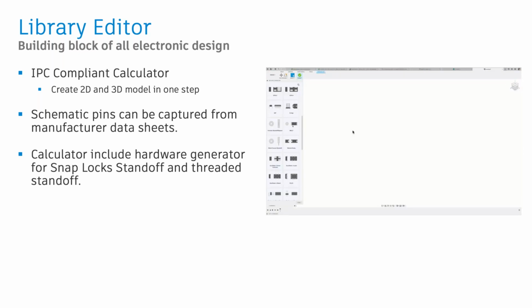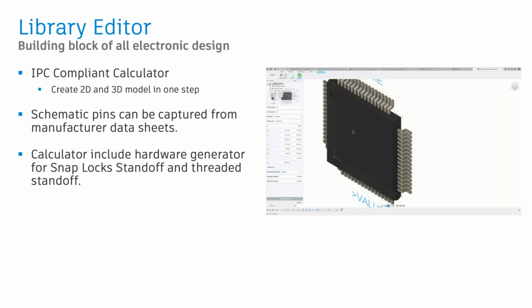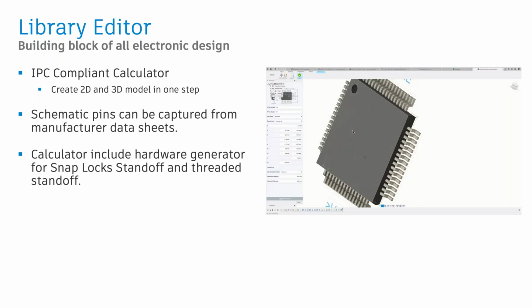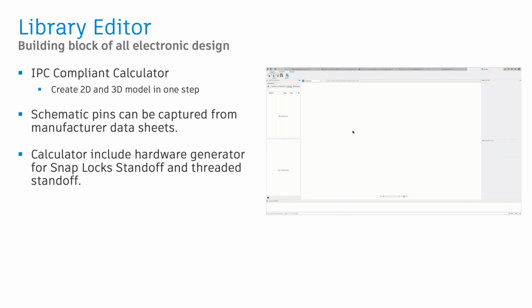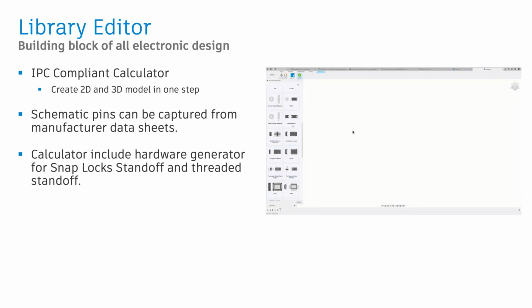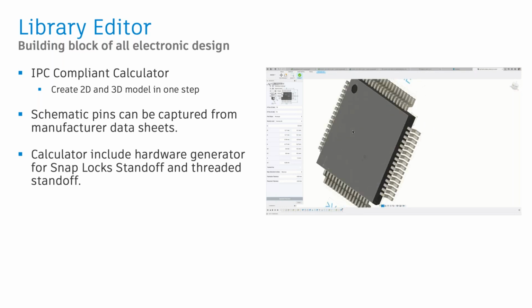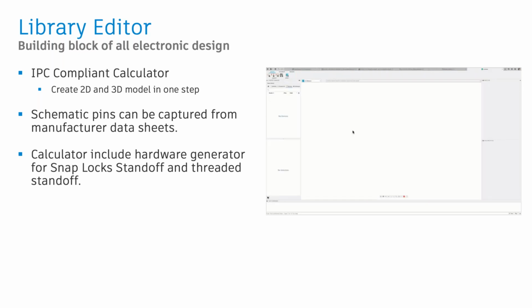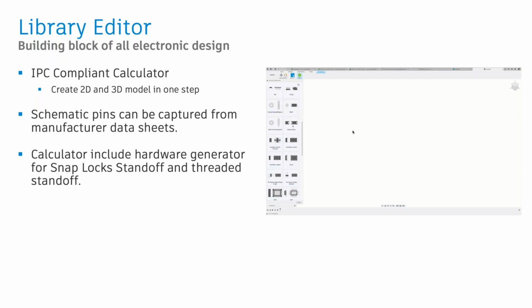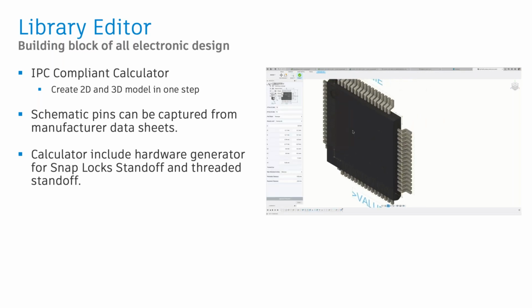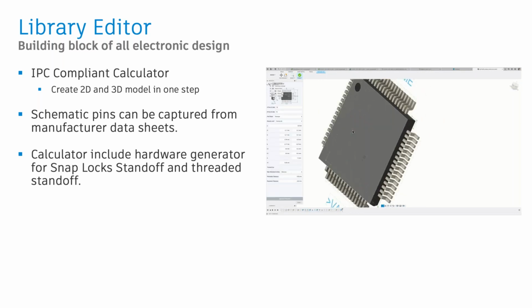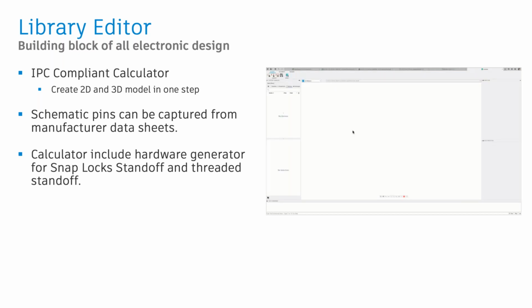And what does this translate to? You may have to actually have the boards made or prototyped. When you get them back, it's possible that the component just doesn't fit. The landings used might be too big or too small. Then you may have to create an interface in which it actually lets you use the component you use. That way it's not a waste of money, or you don't have to send out for another batch. So being able to create this process is not only a time saver, it's a money saver as well.